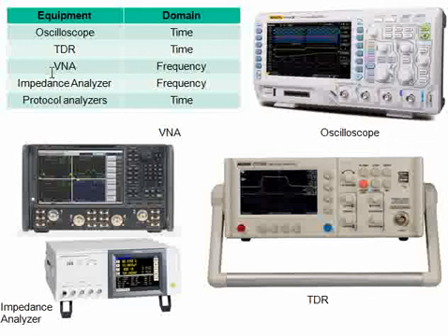And then protocol analyzers are just like probing those signals. We can say a logic analyzer is one example. So in scopes we have mixed signal oscilloscopes. If you see at the top here, the input terminal, other than these four analog channels, these can capture multiple bits at a time. There are separate protocol analyzers available, and in mixed signal oscilloscopes, you also have the protocol analyzer inbuilt along with the scope.